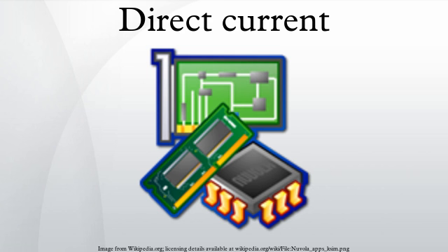Such a circuit is represented by a system of differential equations. The solution to these equations usually contains a time-varying or transient part as well as a constant or steady-state part. It is this steady-state part that is the DC solution. There are some circuits that do not have a DC solution. Two simple examples are a constant current source connected to a capacitor and a constant voltage source connected to an inductor. In electronics, it is common to refer to a circuit that is powered by a DC voltage source such as a battery or the output of a DC power supply as a DC circuit, even though what is meant is that the circuit is DC powered.